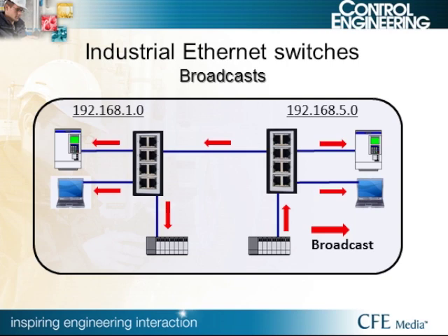As your industrial network grows, you might add different IP networks on the same switch network. This usually occurs when an OEM brings in a new machine and uses his own set of IP addresses. Even though the different networks can or cannot communicate with each other, their broadcasts are received by every device on the network. If one device on the new machine starts excessive broadcasts or multicasts, it affects the entire network.